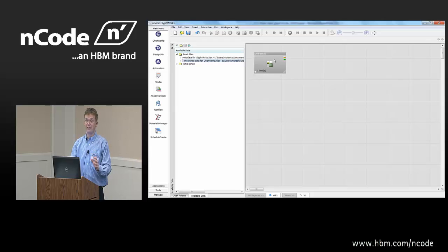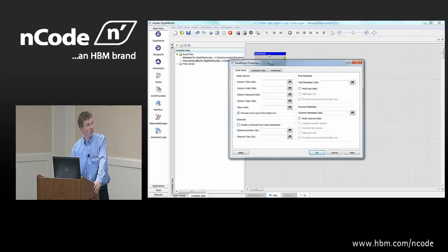Again, this is the case where I have channel data in Excel, but I want to do some analysis in GlyphWorks, because Excel doesn't have a fatigue calculation or a rainflow cycle count algorithm or an FFT algorithm or whatever. It doesn't have that stuff. So I drag this in, I'm going to pop open the glyph properties. Let's take a look at this a little bit bigger.